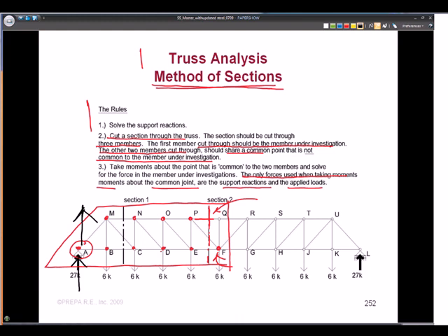So if we push up on this, it's going to try to bend this truss in these directions. And about this halfway point of the truss, this thing is doing the same thing. And so that's where it starts to bend this top chord in compression, okay? So each side, about that half, is being pushed upward. So if you can visualize the top chord being in compression that way, you'll get the same answer. Okay, so it's just visualizing and understanding, do you think it's going to be in tension or compression, and understanding that assumption. Okay, so that's the method of sections.